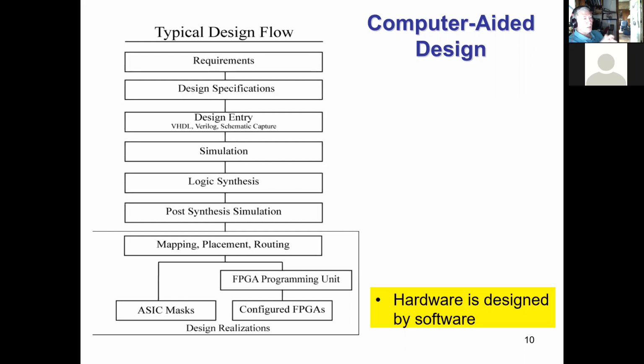We design these very complicated things with hardware description languages. And one of the ways we do that is we create modules. And then once we get the module created and we know it works, then we instantiate it and use it, but we never really look at the details of that module again. And a lot of times we'll have modules where we can change parameters so that we can make them 4 bits wide, 8 bits wide, 16, 32, 64, whatever, and still use the same module.